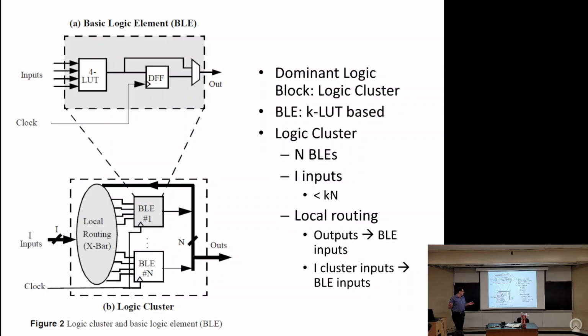So Intel/Altera FPGAs, if you go back far enough, did use full crossbars. Now they usually use essentially a half-populated crossbar. What that means is you take half the switches out. We'll talk a bit more about that later. It means there is now the possibility of this getting blocked, but as long as you don't try to put too many signals through it, it's usually okay.